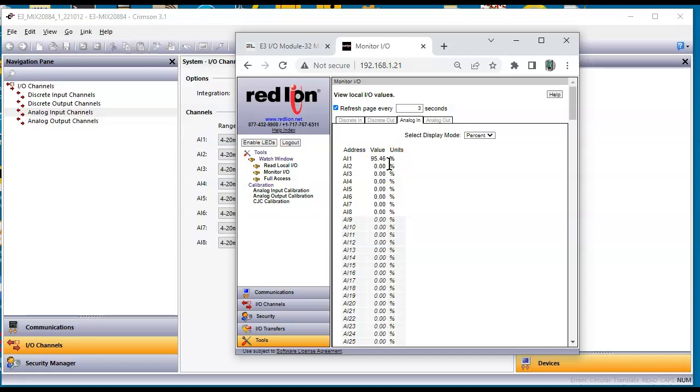Let's stop it at 12 milliamps. Hold on here. There's 12 milliamps. We're sitting right around 49.9%, which is the halfway point. And if we take it all the way down to 4, there's 4.0. Okay, that takes it right below there. If I go to 4.1, I'm sitting probably at, yep, pretty darn close.